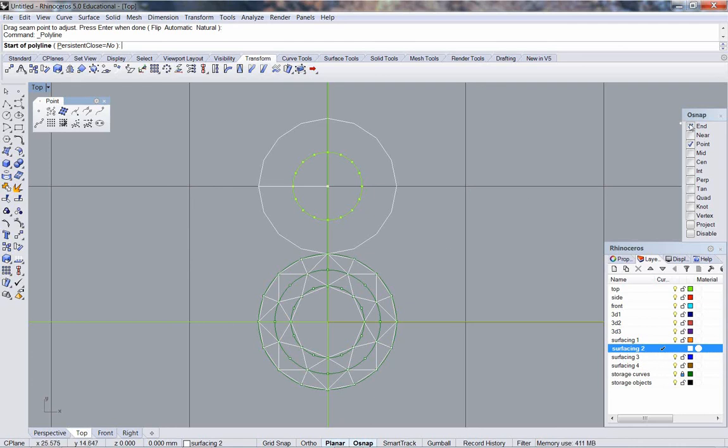We are going to apply end and point. End, point, end, point, end. Okay. Going to array that polar. Once again, the color wheel looking button. Center. Pick the endpoint. We can't type 0 now because the center of this drawing is not at 0. It's here at this grid intersection.